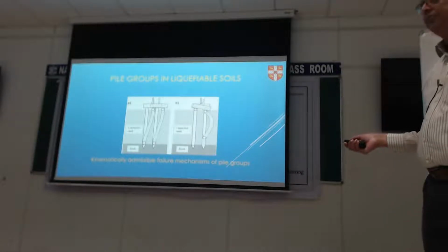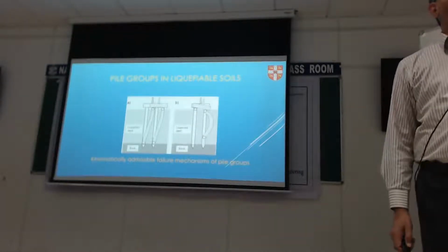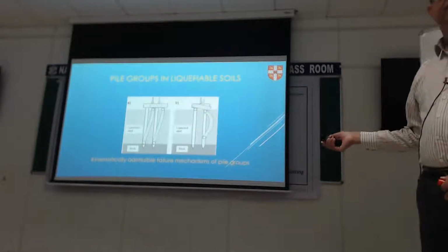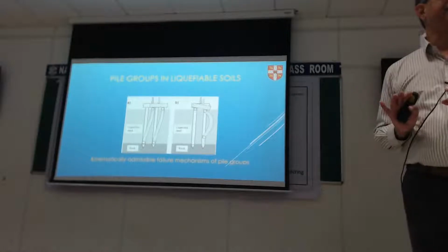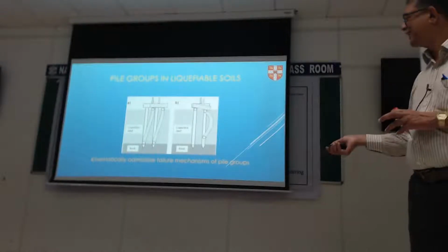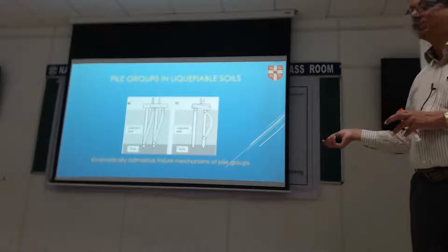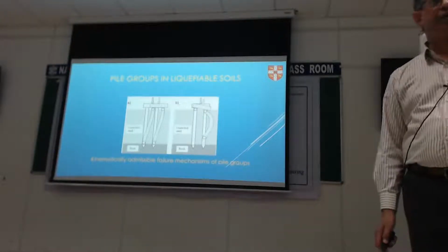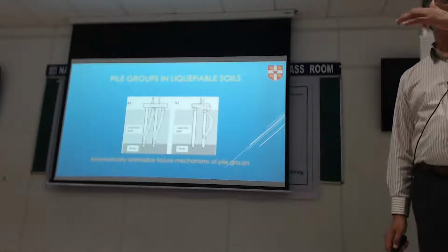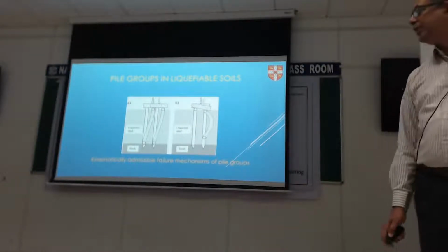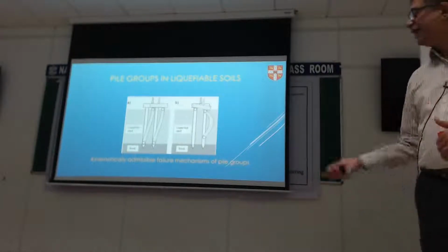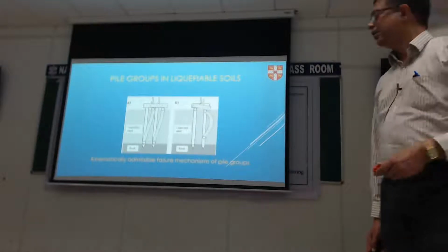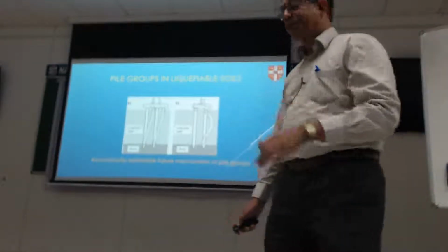Now, depending upon what I said in terms of shear dilation, the location of these hinges can move up, but still it will be a 4-hinge mechanism. So don't take literally that this is where the hinges will form, at the interface between liquefiable soil and the stiff soil. Not true. They can go up because of the dilation effects in the soil, or they can move down if my fixity is not rock, if it is more pliable material like sands.